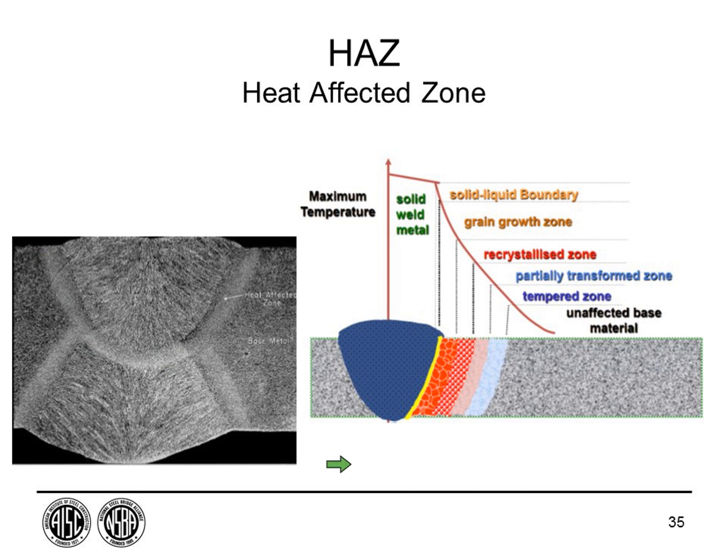So this is shown schematically over here. Again, this is the fusion line, and this is the coarse grain heat affected zone that we're worried about. This is the area where we want to control the cooling rate. Just as an aside, this is the reason why welding a very high alloy steel, like a 4340 that you might use for bolting, doesn't work well. It's a very easy material to harden, and you'll end up with a very hard heat affected zone and possible cracking in that area.